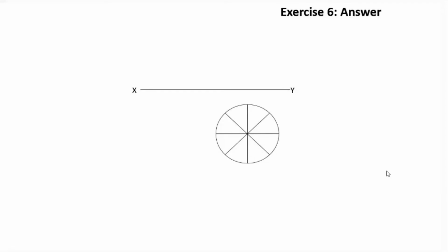So that is also possible if you use the 30 degree, that is 12 equal divisions. In that case, drawing the curves will be easier, but the number of projectors required will be more. Since here we require only 8 projectors, but in the other case we may require 12 projectors.